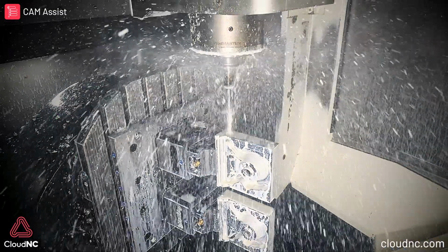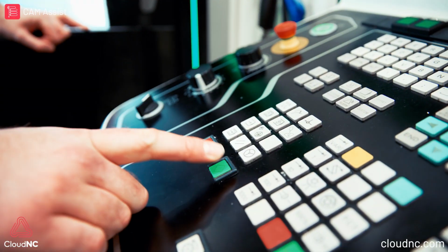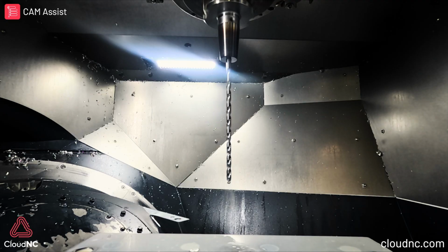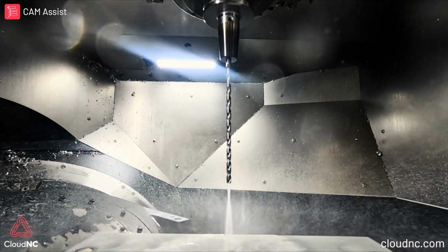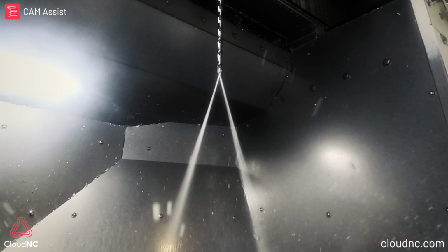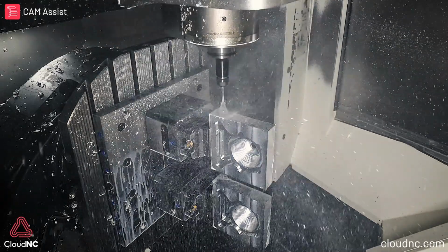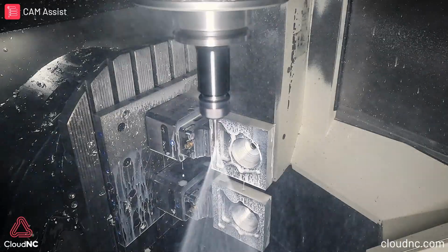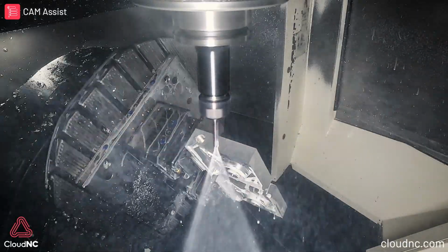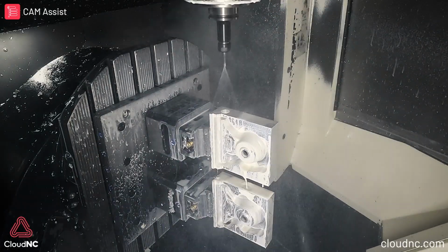As this long series drill drives through the material, there are two key fundamentals that are critical. The first being through coolant. High pressure through coolant is paramount, as it is effectively used to flush chips and prevent overheating. All coolant pressure must be directed to the tip of the tool and the tip of the tool only. Required coolant pressure can vary depending on the drill diameter, length-to-diameter ratio, and the type of material that you are drilling, so it's best to consult your tool manufacturer for their recommended coolant pressure.